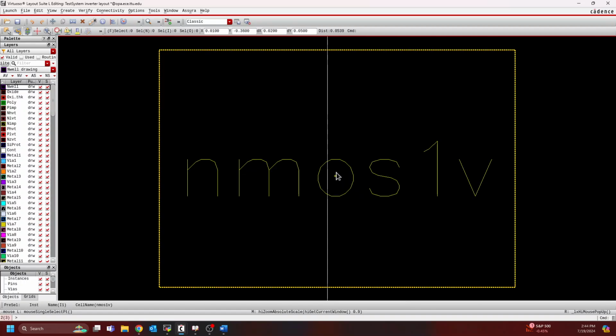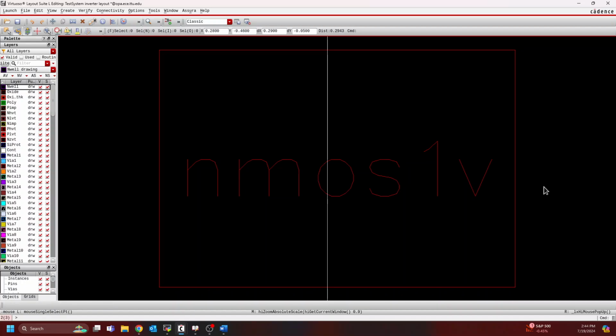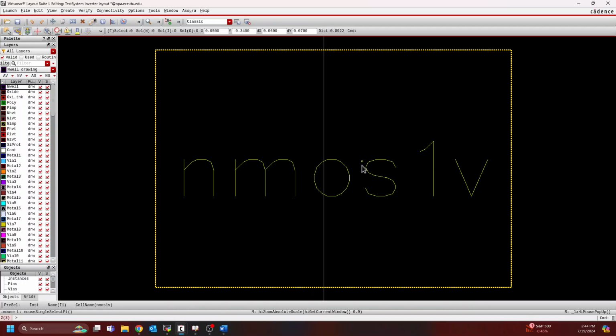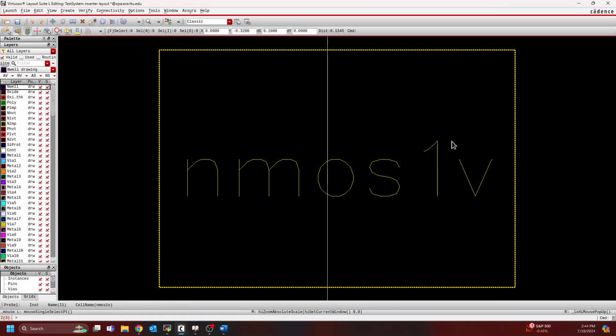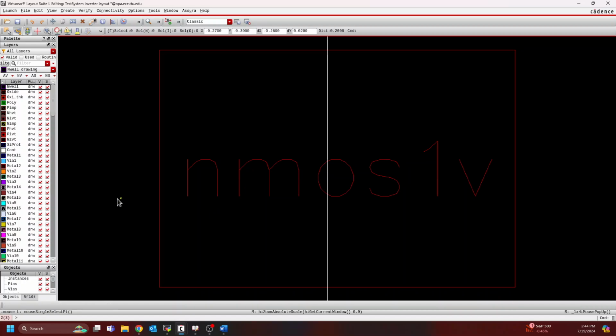And then if I press F to zoom in, we can see that it's just a red square. And this red square doesn't really give us a lot of information, right? Because it's missing out on some things. We can't really see the features, where the drain source connections are. We can't see where the gate connection is. So for us to actually see more detail, we need to show the full view. And for us to do that, we have to do Shift and F.